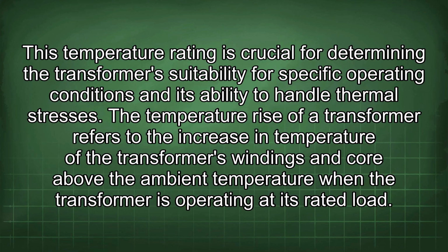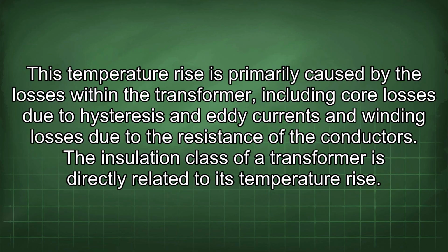handle thermal stresses. The temperature rise of a transformer refers to the increase in temperature of the transformer's windings and core above the ambient temperature when the transformer is operating at its rated load. This temperature rise is primarily caused by the losses within the transformer, including core losses due to hysteresis and eddy currents and winding losses due to the resistance of the conductors.